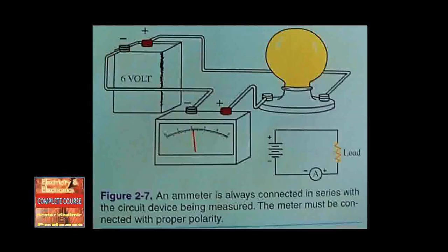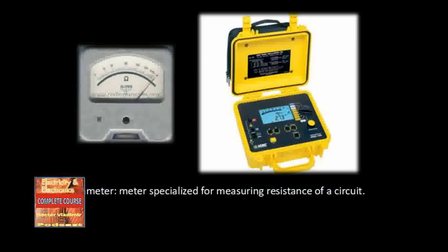It is wise to make a rough current calculation using Ohm's law to determine the proper current range on the meter. When troubleshooting a circuit, it is best to start on the highest possible setting. A faulty component can cause higher currents that would not be normally expected. Again, observe correct polarity, red to the positive side of the circuit and black to the negative side of the circuit. When measuring resistance, be certain that no power is applied to the circuit.